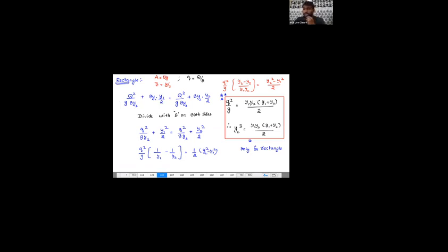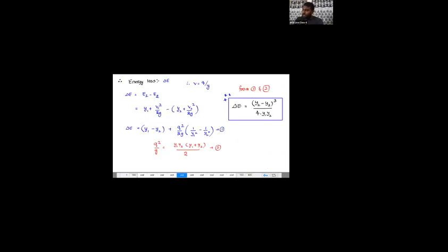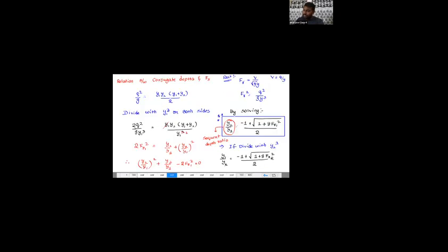Y2. And once I know Y1 and Y2, I can find out the height of jump, which is nothing but Y2 minus Y1. Length of jump is nothing but 6.1 times the height of the jump. Once I know Y1 and Y2, I can find out the head loss also. So this much amount of energy is going to be dissipated. So that's all with the analysis.